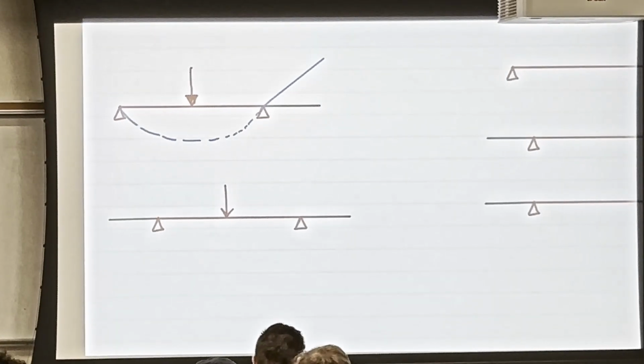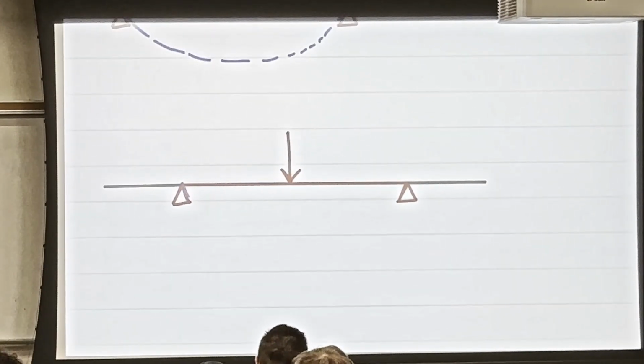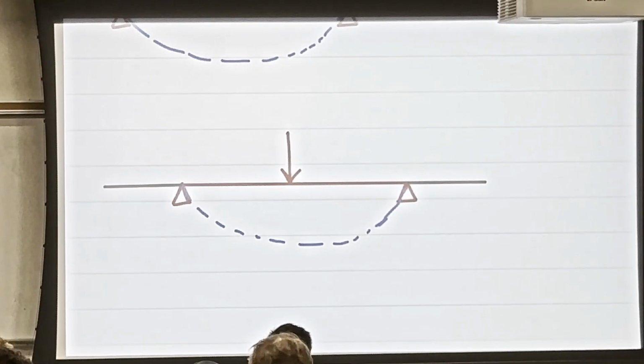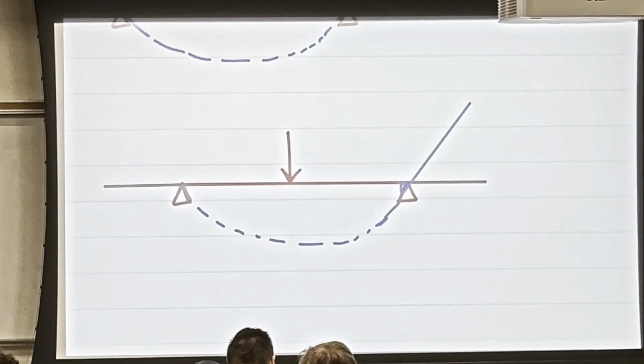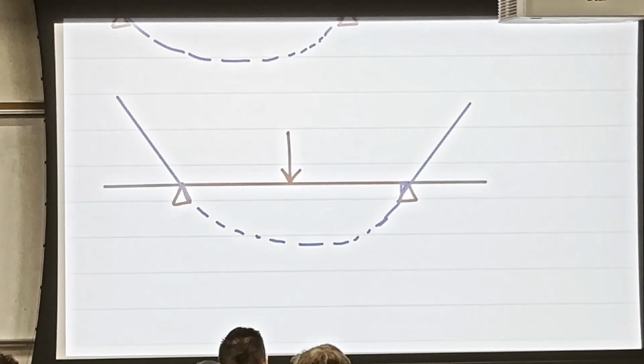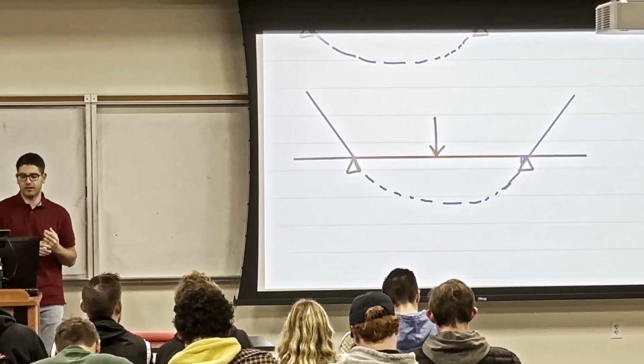So this is for the single cantilever. What if I have both cantilevers? And I'm stressing on this again, the line is going to extend with the same theta here. So I'm going to extend it like this, and I'm going to extend that one like this, with the same theta. Is that clear? So this is how we can draw the elastic curve for beam with cantilever.